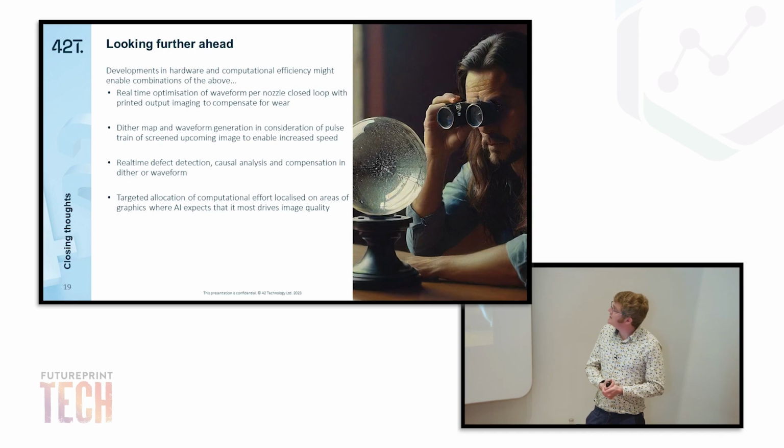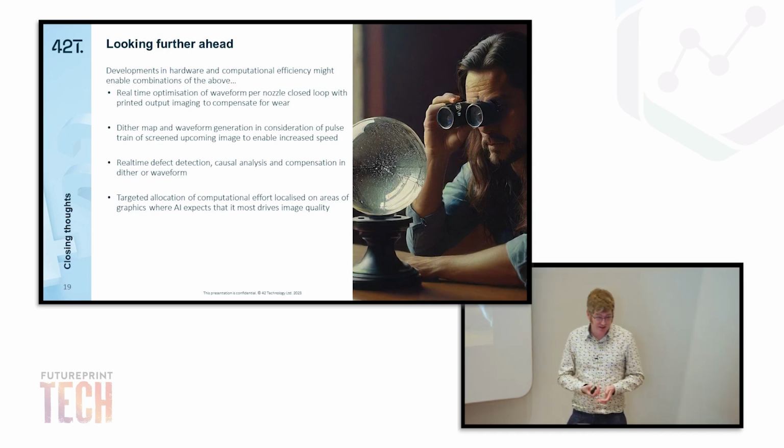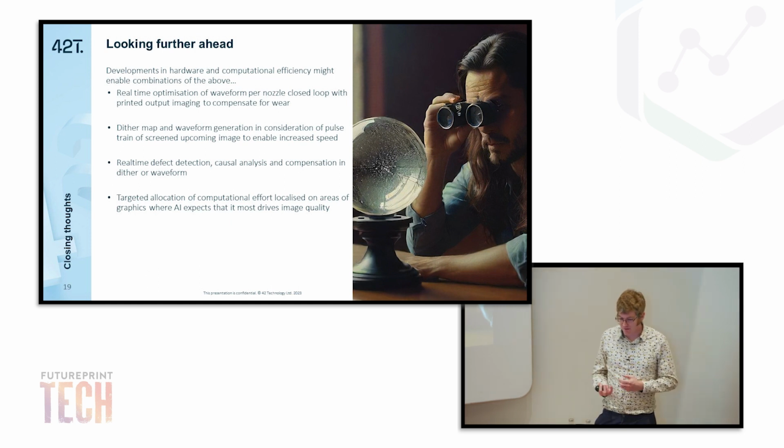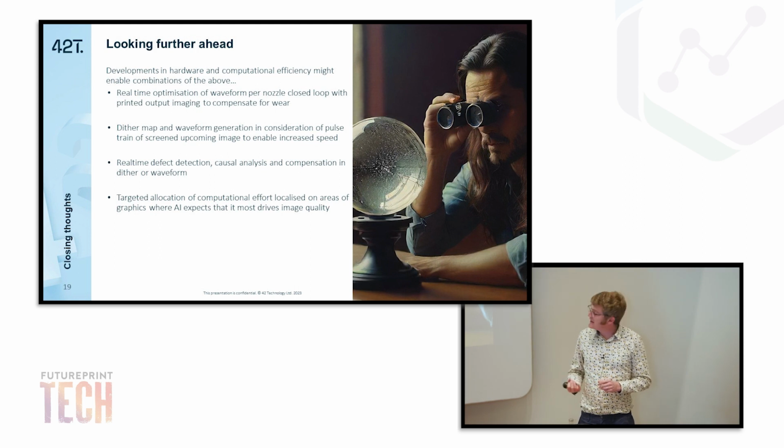Looking further ahead, developments in hardware and computational efficiency might then enable some combinations of this. So real-time optimization of the waveform per nozzle, closed loop with printed output imaging. Actually, it sounds from what Simon was saying a few minutes back that some of this might be closer than perhaps I thought. Dither map and waveform generation in consideration of pulse train to enable increased speed.